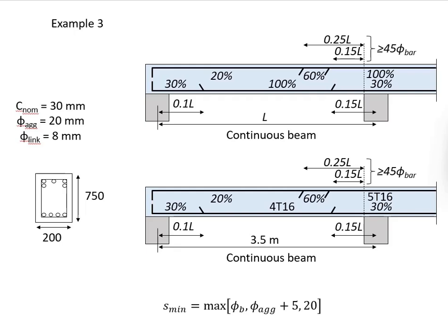At the current stage, you don't know what the layout of the reinforcement will be. The final layout of the reinforcement will be governed by whether the spacing is sufficient, meeting the requirements of the minimum spacing. In order to maximize the performance with the best arrangement of the reinforcement, you will have 4T16 arranged together in order to get the maximum effective depth possible.